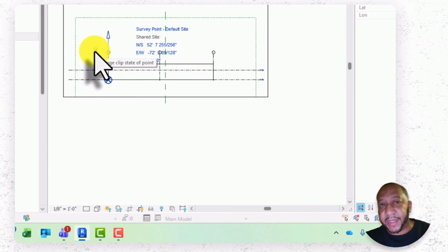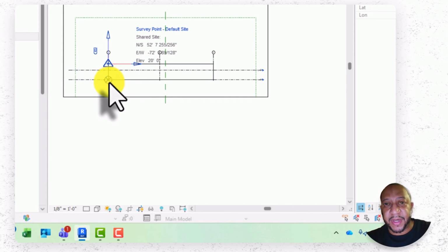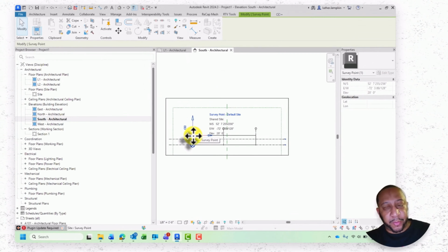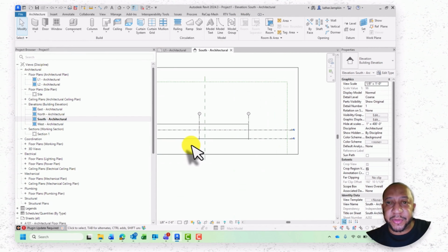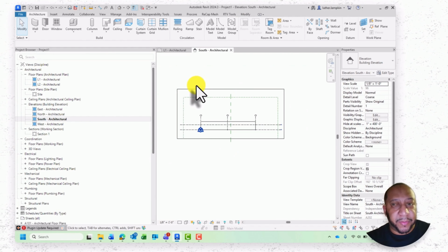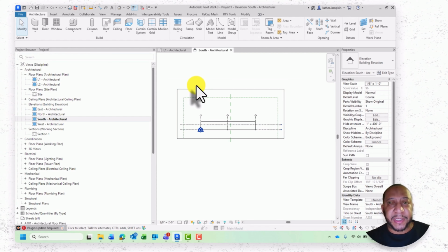And then if I do here and I hit this, now this is going to be the new elevation that comes in. Okay, and I move the same thing here. But we don't want it to. We want best practices to be right here with level 100 for a slab. So this is highly important when we start talking about project base points and survey points.